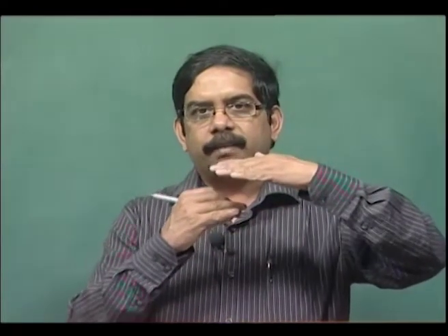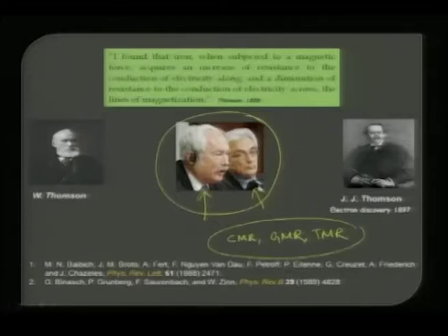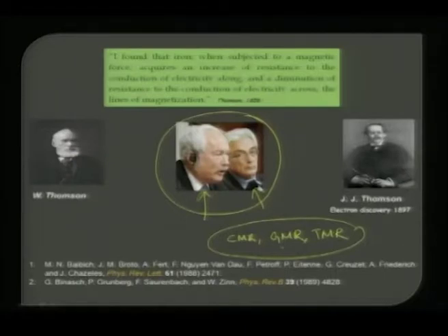if you can maintain these metallic multilayers in a very thin dimension, and they found there is a huge response when you measure such stackings for electrical conductivity. They found there is a huge loss in resistance in the presence and absence of field, and that is what brings to effect the GMR spin valves.